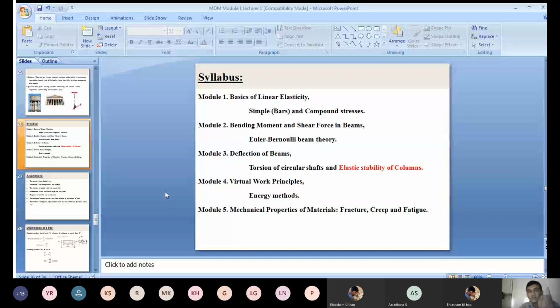You already know what we mean by stress, right? The intensity of internally distributed load over a cross-sectional area is called stress. That is the physical meaning. Mathematically, stress is equal to load divided by cross-sectional area. Symbolically, we represent normal stress as sigma. Load may be F or P, the cross-sectional area is capital A, and the unit of stress is Newton per mm square.